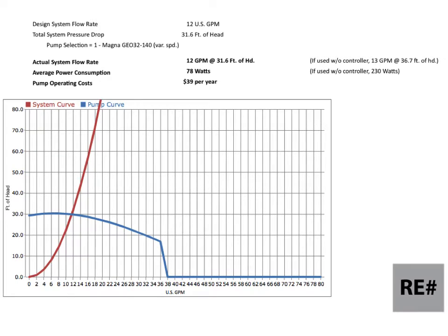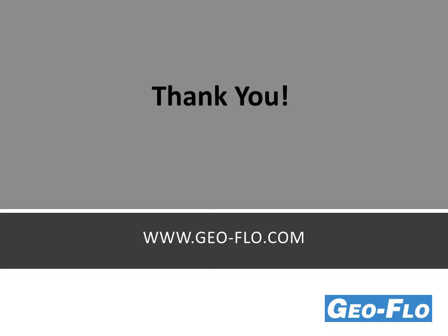If you look at the total COP or EER for the system, when we have very few pump watts, we certainly affect the system EER and COP. So it's a big advantage from an operating cost standpoint. And in many cases, like this example, one variable speed pump can actually replace 2 constant speed pumps if we're comparing to the 2699. I hope this video series was helpful.